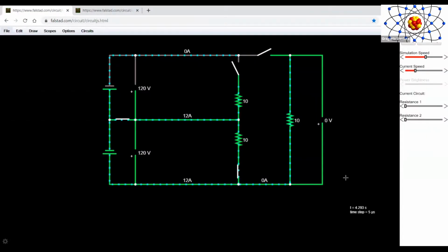And I want you to observe what's going to happen if we have unbalanced loads. In this case, we have an unbalanced load, which is also working. We have an unbalanced load of 4 amps. But if we lose the neutral conductor, then look at what's going to happen. You see how everything becomes awkward?